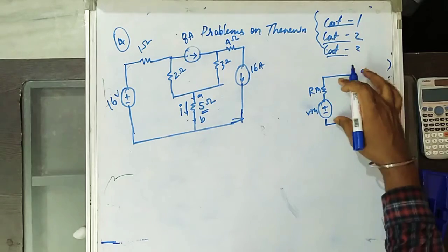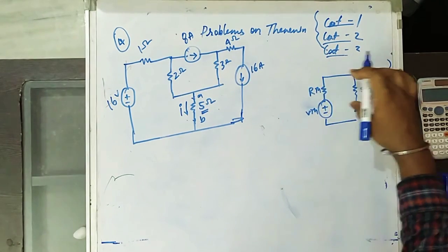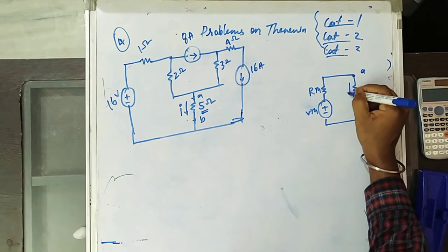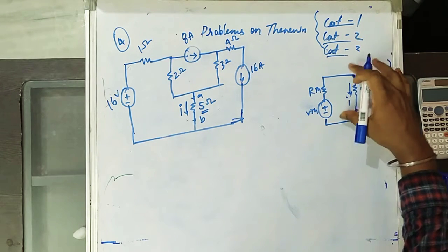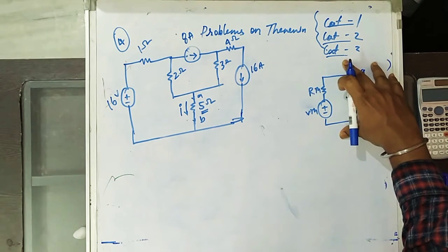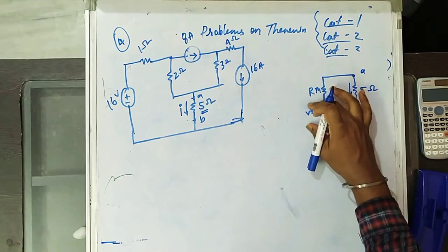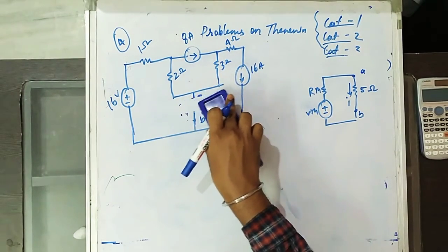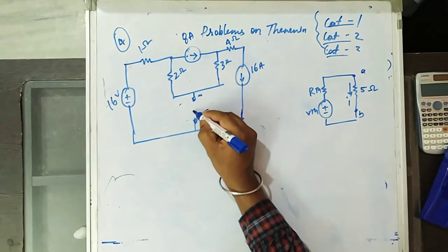So this entire circuit is represented by Vthevenin and Rthevenin, with this 5 ohm target element. If you find current I after finding this Vthevenin and Rthevenin, you will get current I. This is the methodology to find current I by the Thevenin equivalent circuit. To find Vthevenin, in this same circuit, you open that AB terminal. So this is VOC.